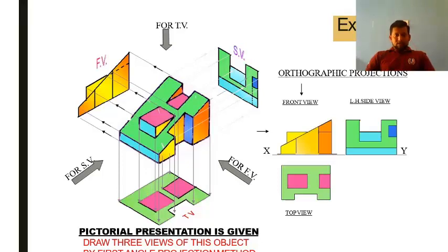So, drawing the front view, top view and side view. It is always recommended to start by drawing the front view or top view, but in general it is recommended to start with the top view. Mostly, the view in which you are able to see more dimensions, that view we will draw first.